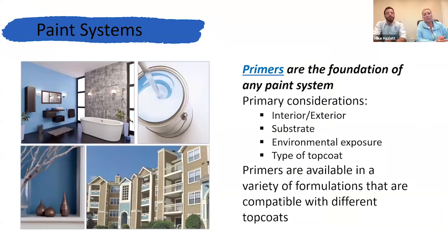All right, so let's get into primers. Let's talk about our primers because they're the foundation of any paint system. Just like our preparation of the surface, once we have a properly prepped surface, we want to talk about primers. We want to take into consideration the substrate. Is it interior, exterior? What kind of environmental exposure are you going to have? Are you by the water where you've got a lot of sea salt? Are you by a major highway where you've got a lot of dirt, grease, and oils from trucks coming by?